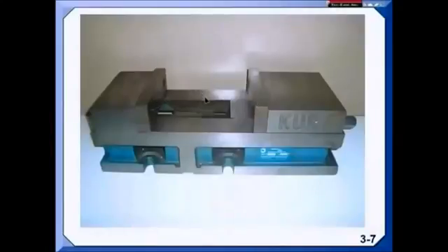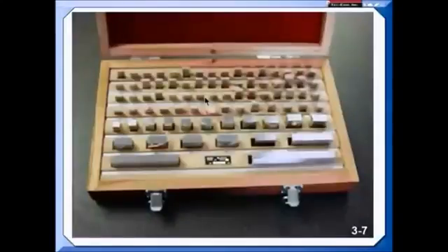Now often I'll have folks from the shop say, yeah, but I don't want to do that. And I understand that, but if I need symmetry, this is what you need to do. If I have a slot, I still can get a center plane. I could fill it with the largest stack of gauge blocks that'll fit in that slot and then indicate off the surface of the gauge blocks.